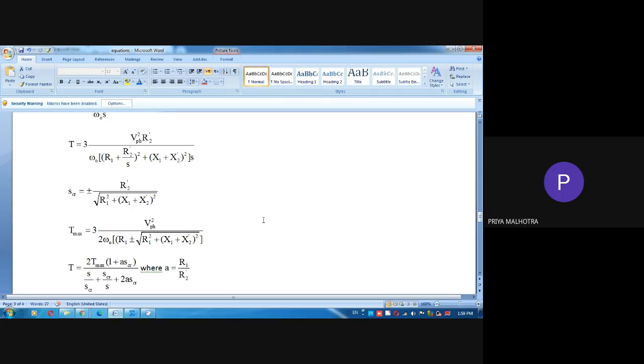After this torque, the motor will not sustain that torque. Yes, correct. This is the maximum or stalling torque. If you increase the load torque above this value, the motor will not be able to carry that torque. It will stop. That is why they have used the word critical, or CR.